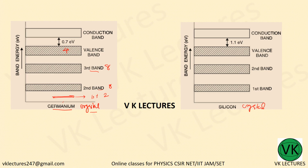Now, to make this valence electron conducting, it should jump to the conduction band. That means each electron here should attain an energy of 0.7 electron volt. If by some means I am able to give this electron 0.7 energy, it will jump to the conduction band and it will conduct.